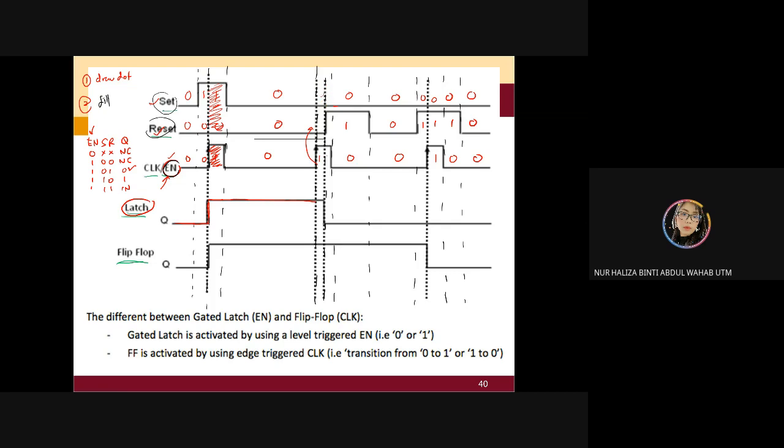So now in this scenario, for 1 you can divide into 2 right here. For these changes, you have 0 and 0, which is no change. You continue until the next dotted line, and you check your input, EN is 1. And at this particular dotted line, it is 0, 1. 0, 1 means 0. So that's why you're going to go to 0. Stop at the next dotted line.